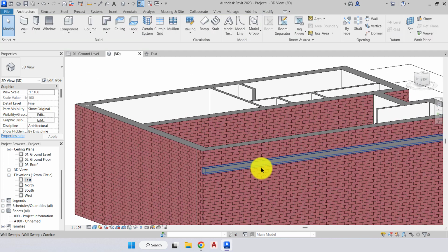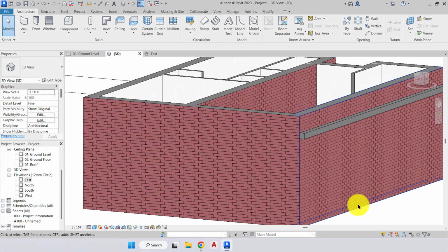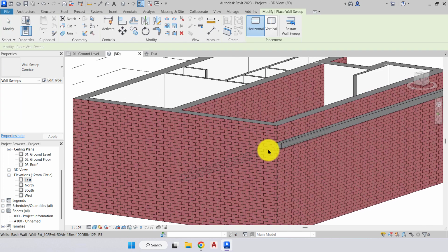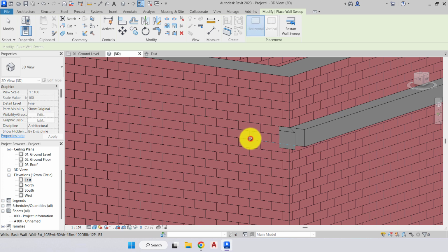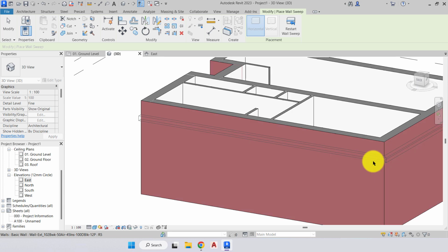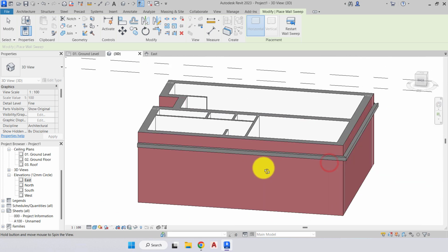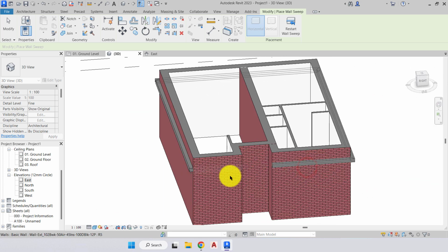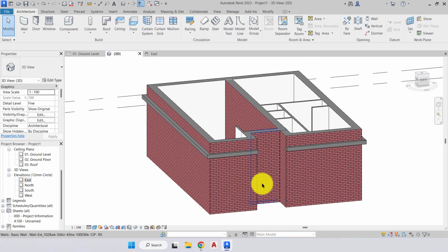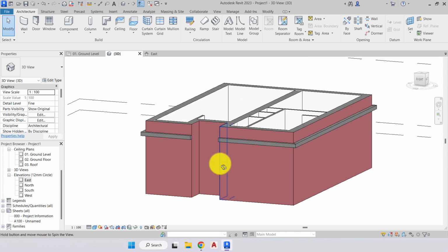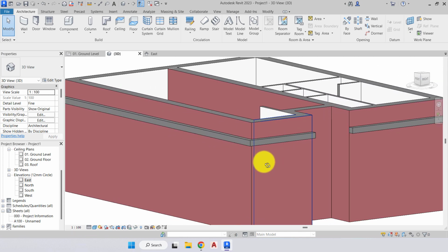So this cornice itself is a basic profile. So now we'll just add in cornice around the building. So what we'll do is we'll come to the back. When we see that dashed line, we know it's aligned up. Orbit around and again place. We'll also feel that the mouse will kind of attach or lock into that position. And then we have placed our cornice.